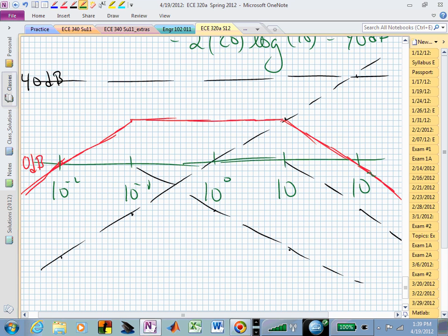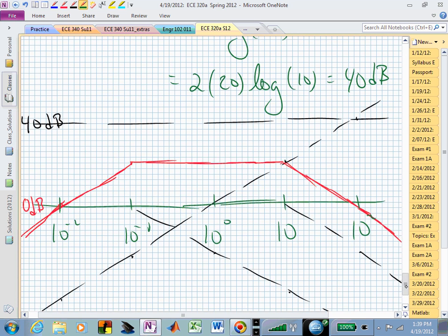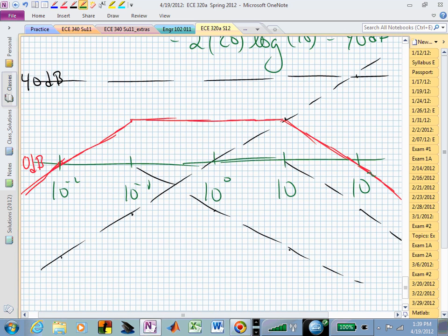Is this making sense? Now you're actually going to be able to design because you know how to create transfer functions that have that shape. You now know that if somebody says, oh, I've got something coming up from way down below at low frequencies and coming up, that's a 0 at the origin.